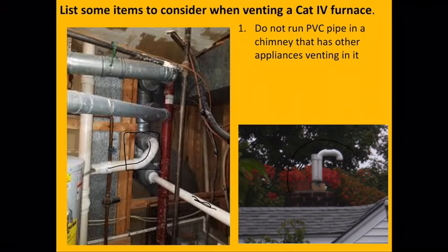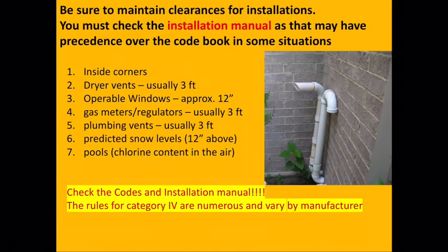You can certainly use the chase if it's a chimney. For example, the image that I have on the far right here is showing PVC vent pipes going into a chimney, and as long as the other vent system isn't, if there's, let's say, a multi-flue chimney, that would be the only reason why I could see that maybe creating a problem for you. The other thing that I would also be a little bit alarmed by in what's shown here is that the separation between the intake and exhaust is really not appropriate. I'm not saying that's a good application, but that's one that you'd have to be careful with.